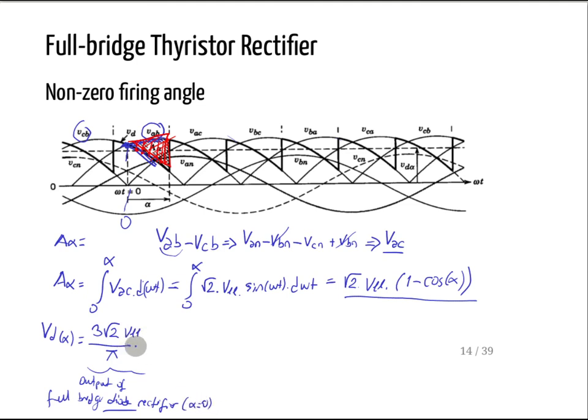So minus, I want to get that voltage drop. Again, this is not volts, this is volt-seconds, or voltage radians. So how many times do I have that voltage? I have 1, 2, 3, 4, 5, 6, 6 times divided by 2 pi.